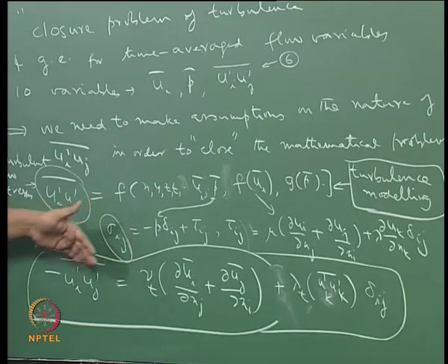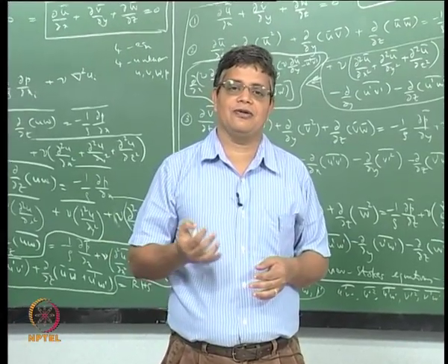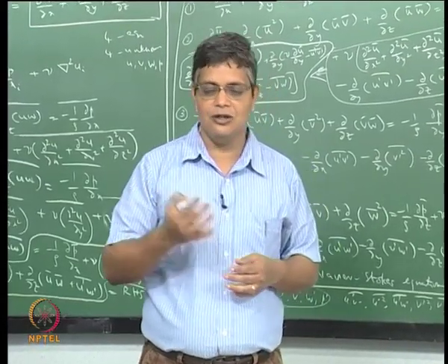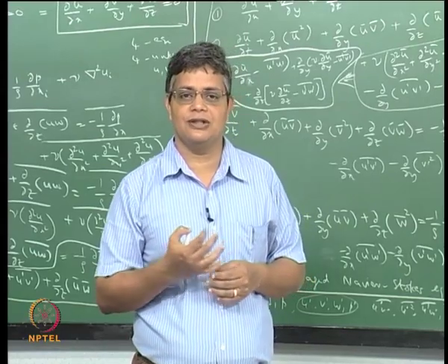This also is consistent with the general observation that in turbulent flow we have additional momentum flux which is causing additional friction factor, and an additional mechanism for heat transfer and mass transfer. That is why we have higher heat transfer coefficients and transport coefficients in turbulent flow.